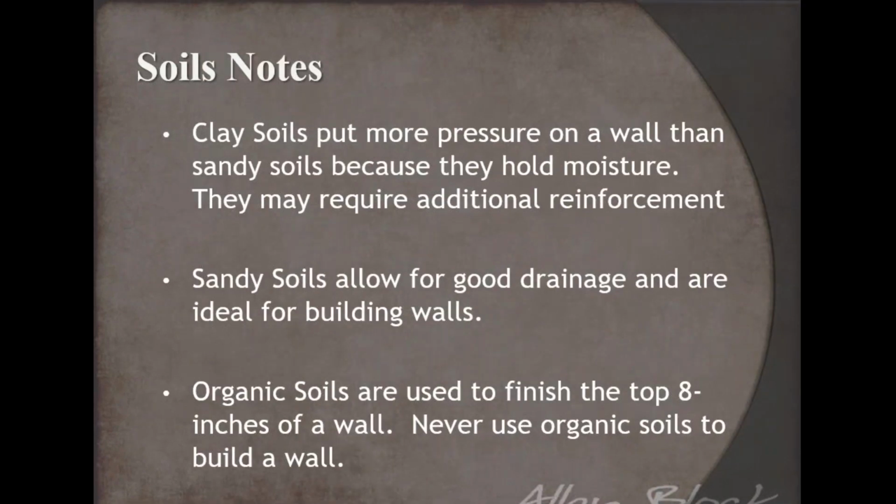And really, when it comes to retaining walls, we know when we're building in clay, that clay will put additional pressure on a wall, and that's all important. But it probably will require some additional engineering and maybe some reinforcement. Sands and gravels, we'll get into why that's great, are a little less sensitive to the moisture because they will drain and consolidate a little easier.